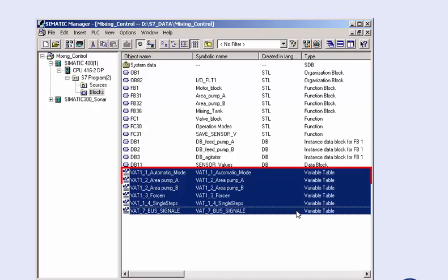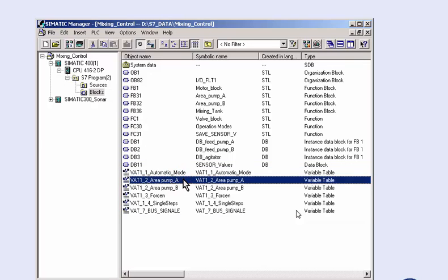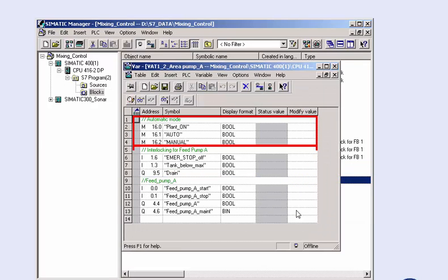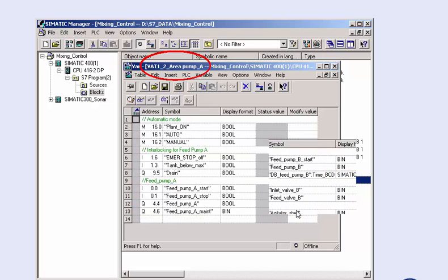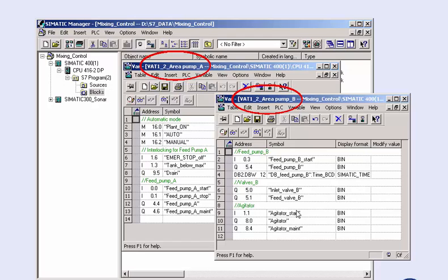These tables can be generated in the implementation phase and saved in the offline project. You have the option of commissioning individual machines, plant components, or also compiling individual variables for certain commissioning sections. This enables you to fix planned test processes in a reproducible manner. This table can later also be used for servicing and maintenance purposes.